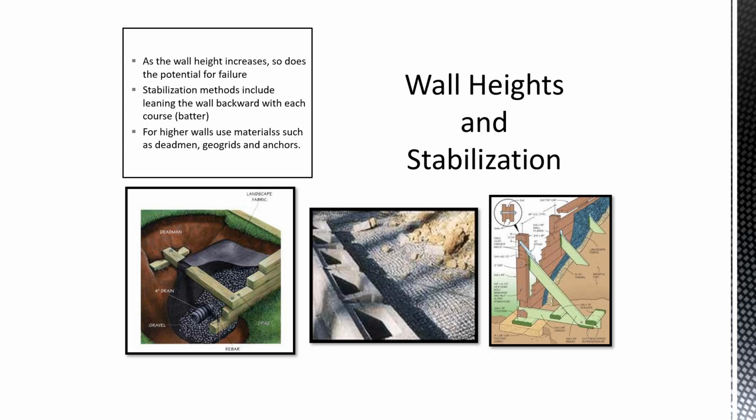These anchors on the right, a little tough doing that, but that geogrid there in the middle section and definitely your dead men will actually keep that wall stable and from tipping over.